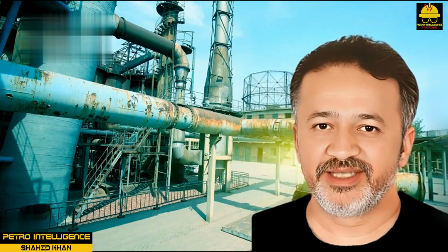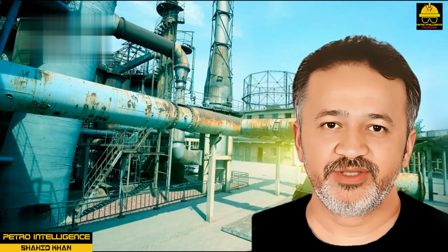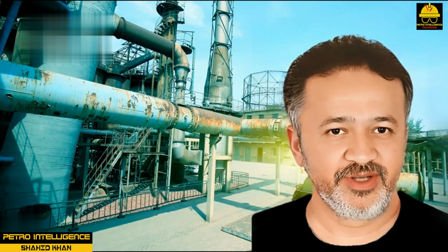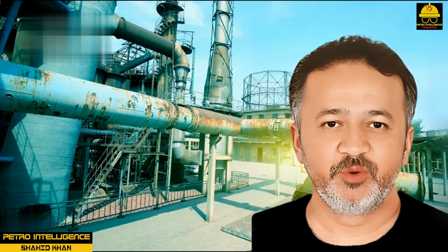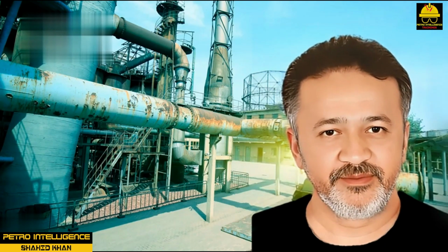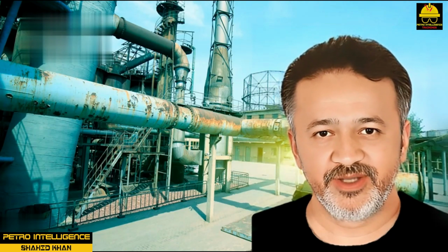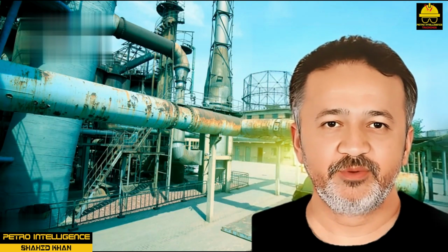The SHP steam is generated by a boiler and is supplied to the SHP steam header. The typical pressure of the SHP steam is 1000 to 1200 psi. SHP steam is supplied to turbines, which drive compressors. In order to control the pressure in the high-pressure steam header and to transfer excess amount of high-pressure steam to the high-pressure steam header, a letdown, pressure-reducing, station is provided between the SHP steam header and HP steam header.